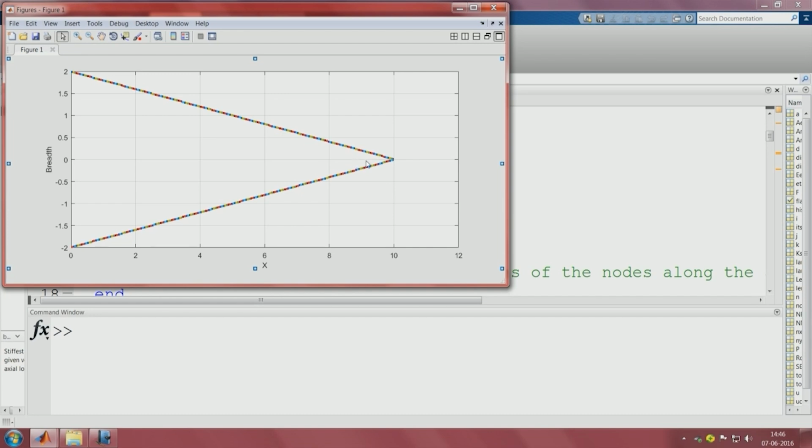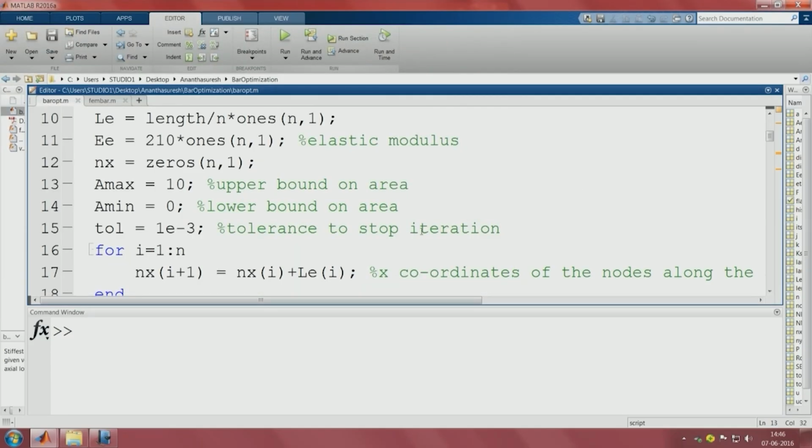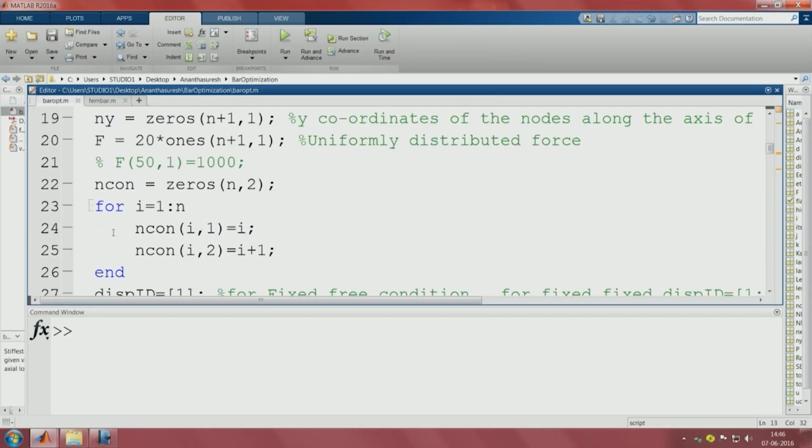This is what we had solved analytically, but now we have a numerical one. When you have a numerical program, we can put any boundary condition and any loading. We can put the loading whichever way we want. So, here the force which I had commented, let me remove that, and no load there. Here I will put the load at the last point, the rightmost point. We have fixed the left one, I made it n plus 1, meaning the n plus 1 node, the last one, extreme right node, that is where I am applying 1000, and everywhere else I have 0 force. Let us see what solution comes up here.